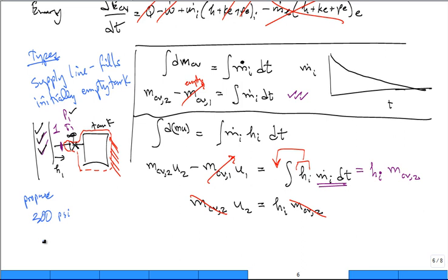Let's say the supply line is 80 degrees F, right? So now I open that valve, in rushes, I'm watching the pressure on the tank, or I'm weighing it. That's usually what they do. They weigh it, if they have it figured out. When it gets up to a certain weight, and then it's 200 psi, and I shut it off, if I had a thermometer on that tank, what would it show? Would it show 80 degrees F? Would it show higher than 80 or lower than 80? The answer is right here.